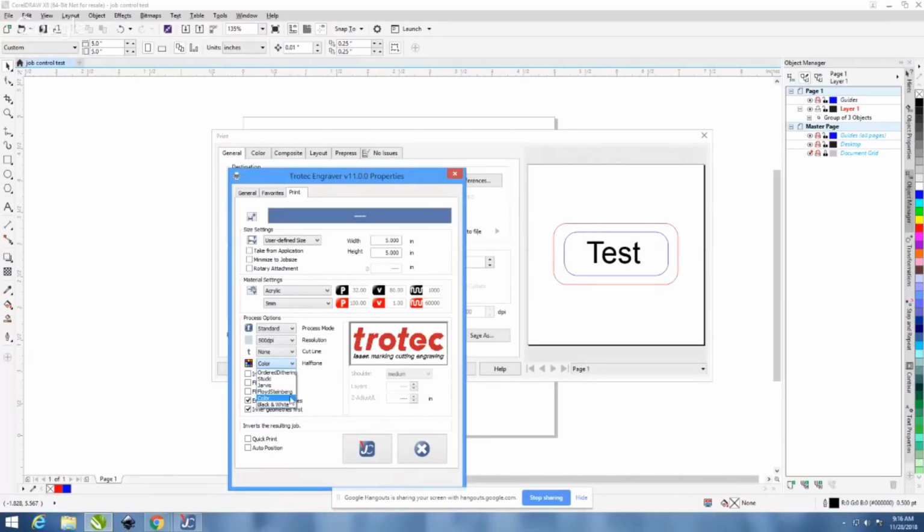Yeah, so for a lot of the videos that if you guys see us doing kiss cutting, we do the blue line or the red line as a kiss cut, and then we do the other color as a full cut. That's right. Also for engraving, if you're doing different colors, you can set different depths in your engraving. Like we did a cabinet drawer a couple of years ago, and we had the Canadian coat of arms had 3 different colors, and it was actually 3 different styles on the wood. So it's a little different from the relief mode where it adjusts. It'll do the job 3 times, 3 different engravings, but it depends on what you're going for.